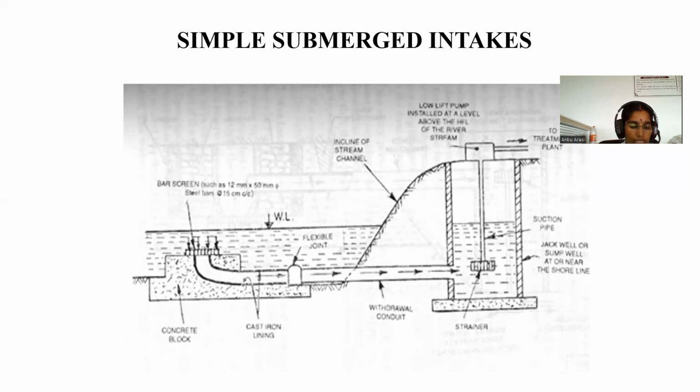In case of lake where silt tends to settle down, the intake opening is generally kept at about 2 to 2.5 meters above the bottom of the lake, and thus to avoid the entry of large amount of silt and sediment. Such intake structures should be placed in streams or in lakes at a place where they may not get buried under sediment and where there are deep waters.